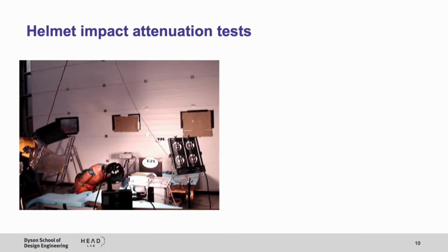As you can see with this drop test, we are measuring the accelerations of the head during that collision, during that impact with the anvil. So we have sensors in the head form that are measuring that. But the question I was trying to answer with this experiment was whether having the body attached to the head has any influence on the performance, on the kinematics of the head.